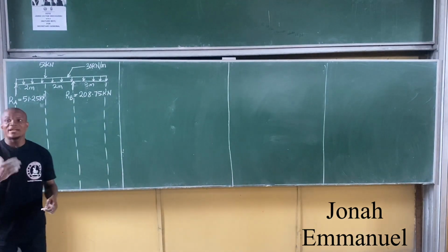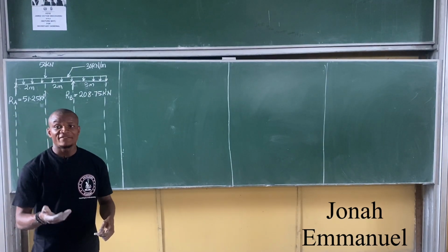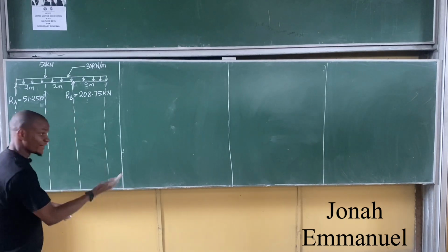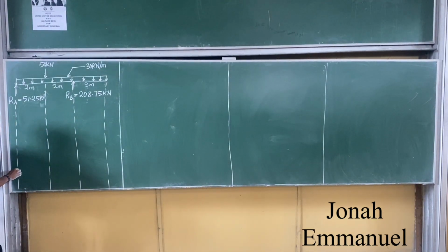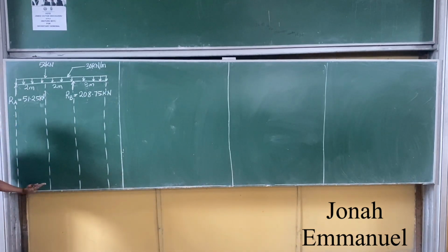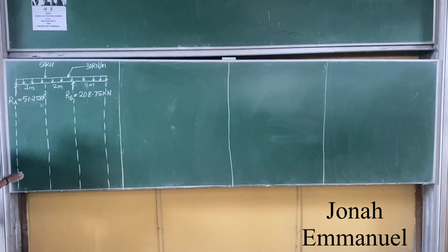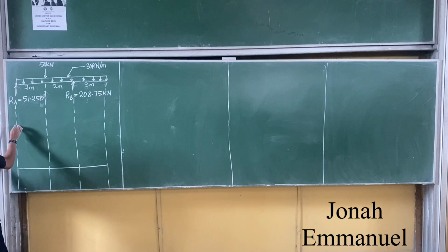Please check. For bending moment, do I have negative values? Check. I have negative value. So what does it mean? It means to slope downwards. So hence, raise the datum. So I will draw the datum somewhere upwards, somewhere here. If you check previous example, we used to draw that in here. Why? We had just positive answer, so to go upward only. In this case, I'm having negative value. That means the bending moment diagram got there to slope downwards. So catch that with up. Somewhere around, let's say here. Let's draw here. Alright, shear force somewhere around here.